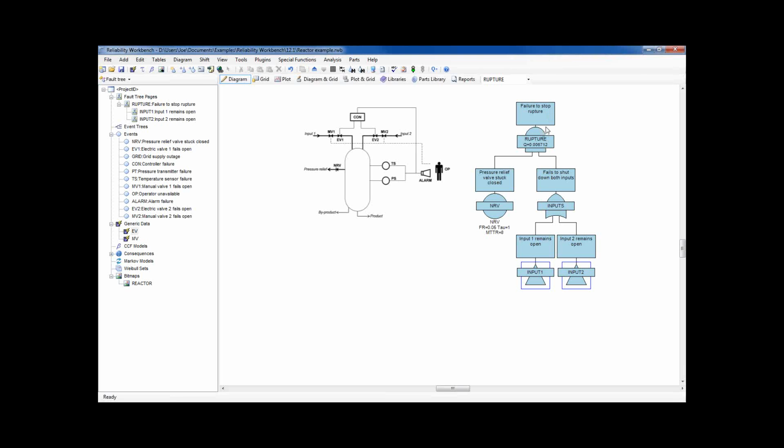So what we've got here, sometimes, for those of you from safety systems or who work with safety instrumented systems or safety instrumented functions, you'll probably recognize this as the PFD, probability of failure on demand. It represents the probability that, should a runaway reaction occur, we can't stop it and it will lead to a rupture of the reactor vessel.